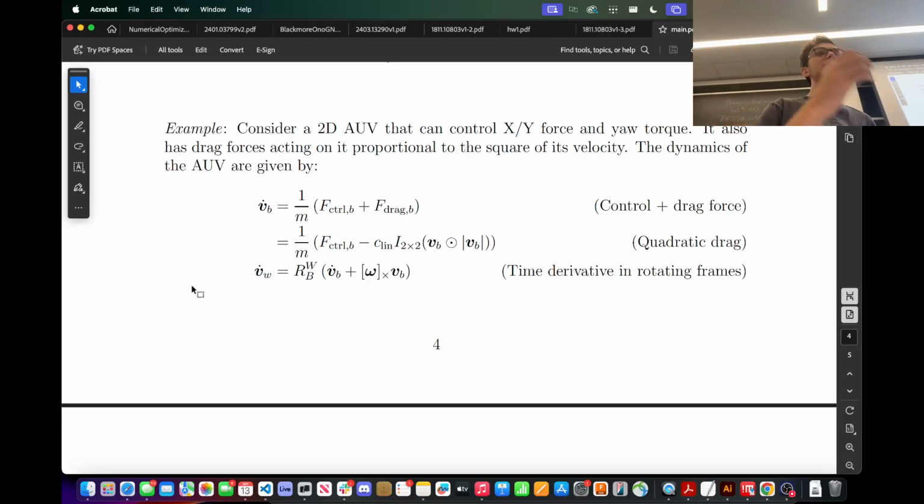So the mass properties usually come from CAD. I'm going to say what usually happens and then what we do. What usually happens is they come from CAD, and the hydrodynamic and hydrostatic forces come from a computational fluid dynamics simulation. You put the vehicle into a flow of water and it can tell you things like, what's that quadratic damping term, what's that linear damping term.